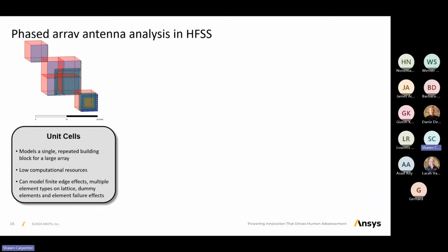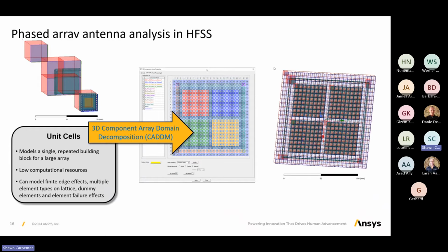And so we have the capability to break an antenna down, particularly periodic antennas, into unit cells and design phased arrays. This design process begins by optimizing a particular unit cell, then setting it into the context of a larger array. Some of these cells may be just things like the corner. They don't actually have antennas in them, but they represent part of the finite structure of the antenna, which will be important on the matching characteristics of each element as well as the radiation characteristics.